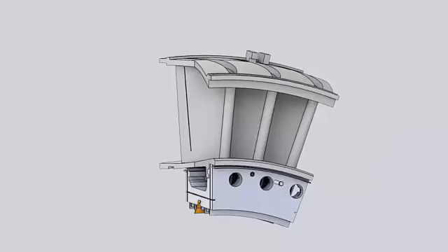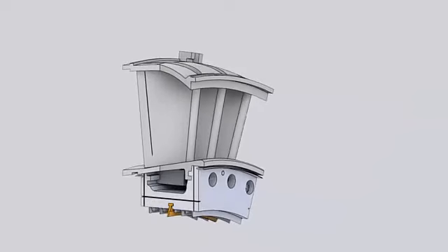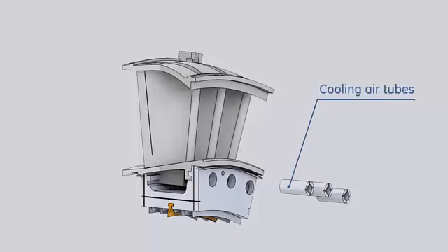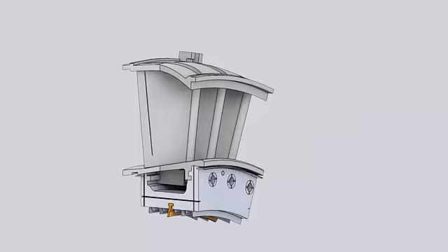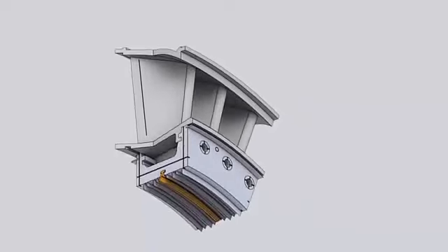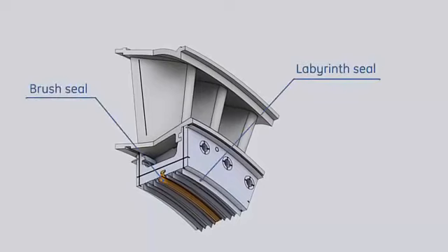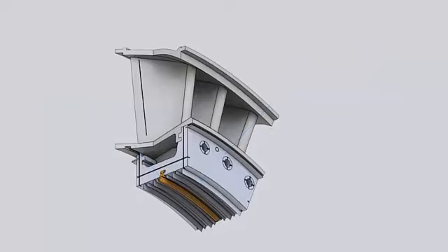These diaphragm segments prevent hot gases leakage past the inner sidewall of the nozzle and the rotor. A high-low labyrinth seal is machined on the diaphragm inside diameter. These seals mate with opposite sealing lands on the turbine rotor spacer.